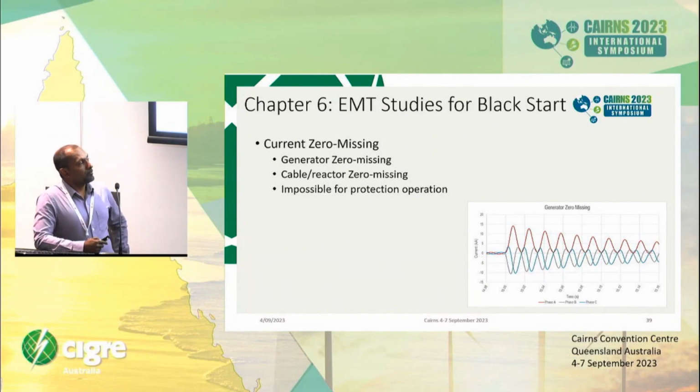Due to the generator operation, the generator is quickly moving from subtransient to transient to the steady state impedances. Due to that, your short circuit currents become smaller, and if that happens at a faster rate than the actual DC component damping, you may see that your current waveform may not cross the x-axis. In other words, it may not get a zero.